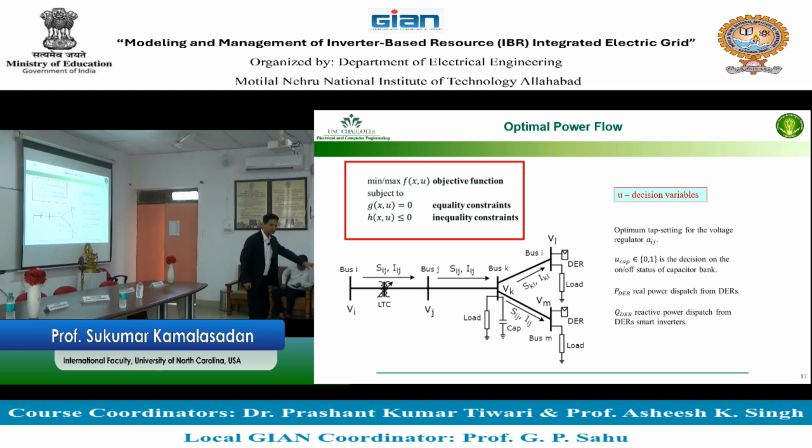device. So optimization is done, optimal power flow is solved, you take the output of the optimal power flow, and you give that as input to the device. That input to the device is, from the optimization side, what we call a decision variable. For the device side, it is a set point. That set point is used by the controller of the device to make sure that it reaches the set point. So that's the relationship between optimization and the device level control.